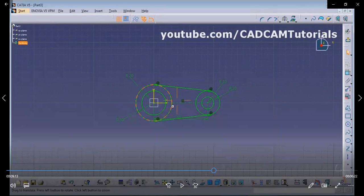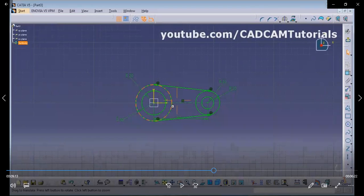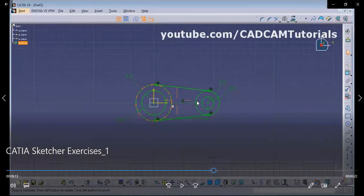To save time, there is a useful feature in line also, an option called bitangent line, which you used. We can use it to draw a line tangent to both the circles, the smaller one on the right side and the bigger one on the left side. Now we don't need this one, so we will trim it off.